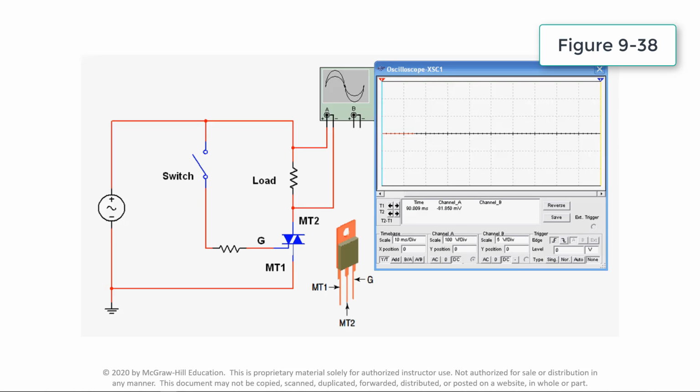This video demonstrates the operation of a triac switching circuit. A triac is essentially equivalent to two SCRs joined in reverse parallel with their gates connected together. The result is a bidirectional electronic switch that can be used to provide load current during both halves of an AC supply voltage. A triac may be triggered into conduction by either a positive or negative voltage applied to its gate electrode.